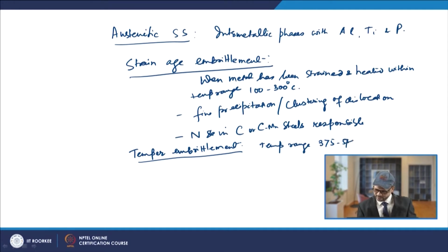So, this is 575 degrees centigrade. This is basically the tempering temperature range, as we all know. Once you do the tempering in this range, you have the formation of undesirable transformation products, and that is formed through the grain boundary segregation, and that basically leads to the decrease in toughness or increase in the embrittlement.